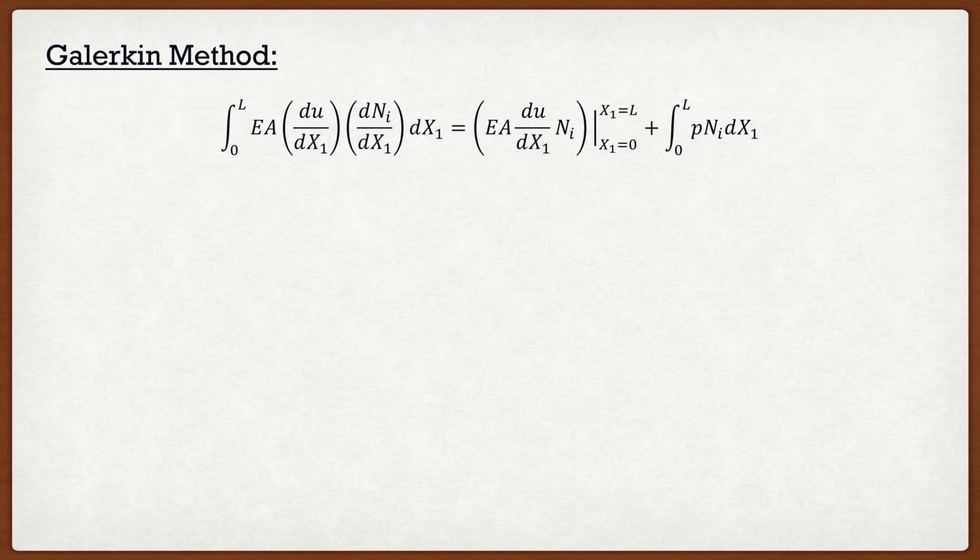Now this equation has something very special, and that is this term right here. If we look at this term, we see that we have the elastic modulus E multiplied by area, and then multiplied by the first derivative of our displacement function. Now we go, hold on one second, isn't that first derivative of displacement equal to strain? Well, of course. So this term right here is actually the concentrated loads at the nodes, because if we take EA and multiply it by strain, we get a value of force. So these are the forces that we apply at the nodes initially.